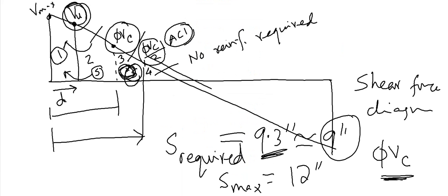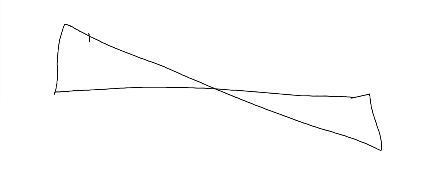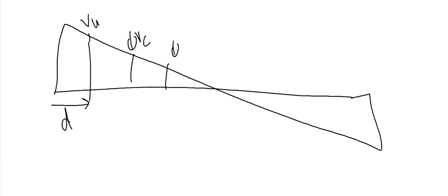So okay, I will wrap up here. In the next video I'll show an example, but if I do it quickly here, draw your shear force diagram, show your Vu at d distance, then locate your ΦVc/2. In this region we do not need any reinforcement. We need some here, because the code says here we obviously need the reinforcement. Whatever spacing we get here, we'll copy paste here.